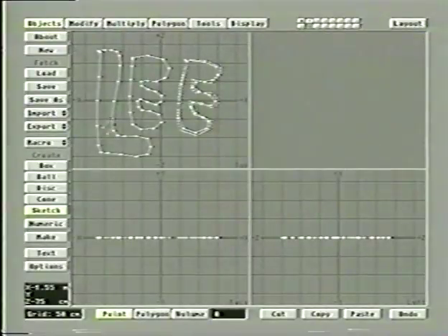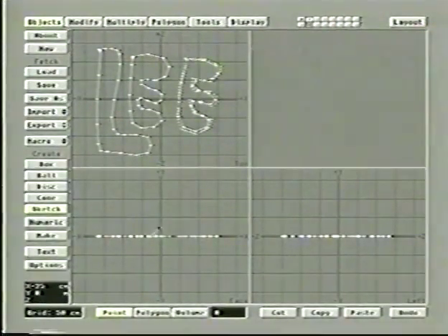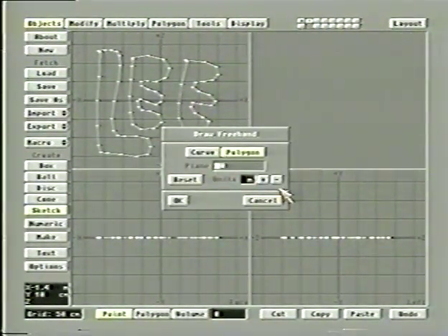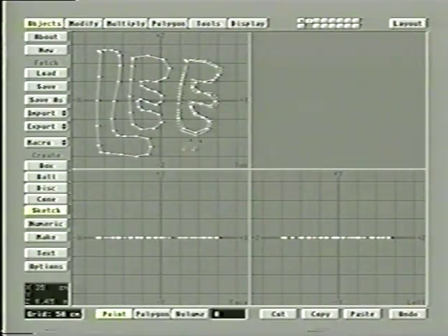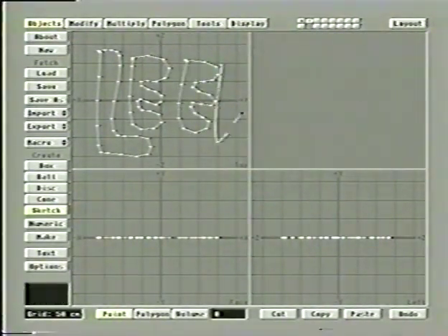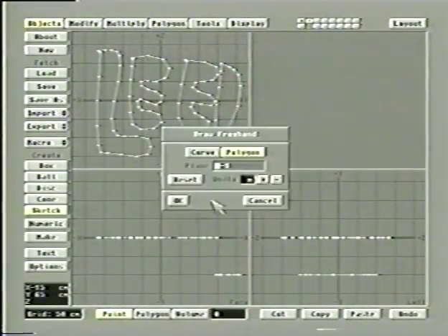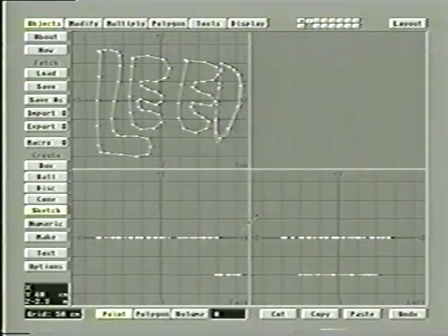The one other option here that you have in the numeric one shows you which plane you're moving it in. In other words, you're drawing this, let's say, from the top view here. Well, it automatically puts it to 0. If, on the other hand, I go to the numeric option, I can choose another plane, such as -1. And what this means is the next thing that I draw here, you see it's drawn at -1 meters, because that's what we had selected here, 1 meter for our units. So it drew it at a plane of -1 meter this way. So in other words, since we're drawing on the front face, it knows, okay, draw it normally there, but it's got to figure out where to position it, and you can select that numerically.